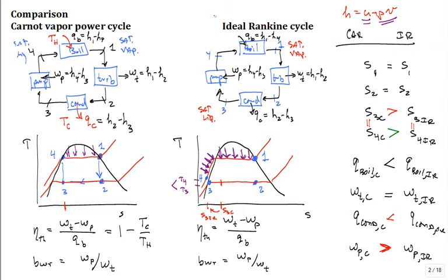Oh, I can sketch it on the diagram and make it look like, hey, I know that one perfectly. And then I can go into a computer code and make it work, where I can get it numerically pretty well. But analytically, by hand, using the tools we have available, sheet and paper, pencil, not for steam. Air, ideal gas, yes. Also, it's very easy for the incompressible substance because PV is a straight line up. V is constant, and so that's easy to justify.